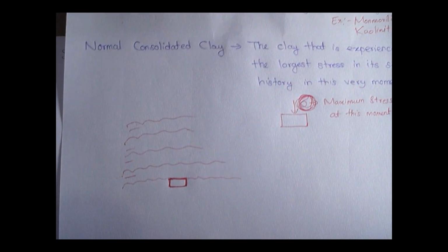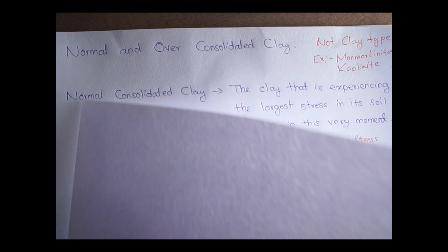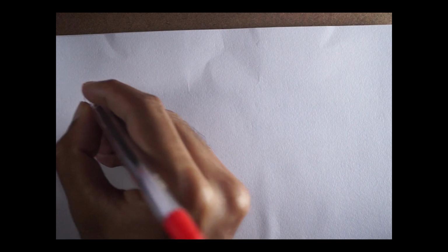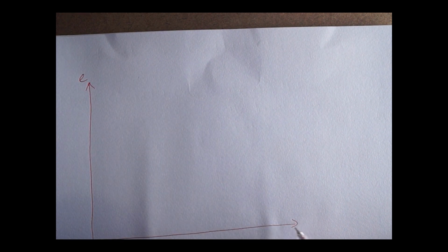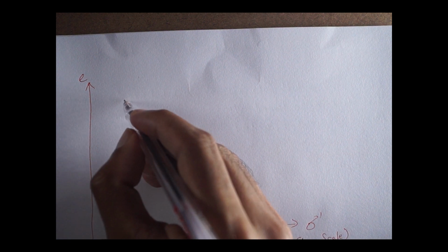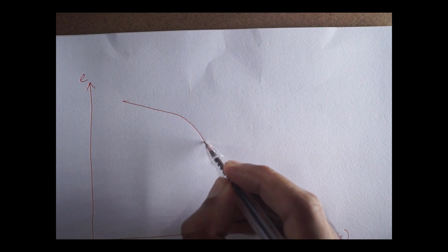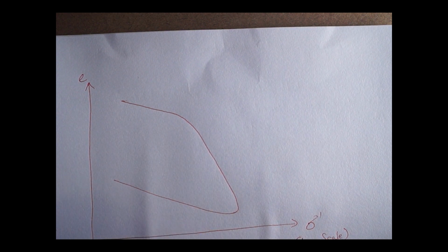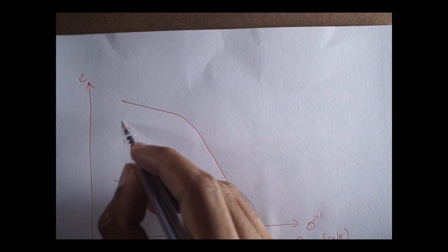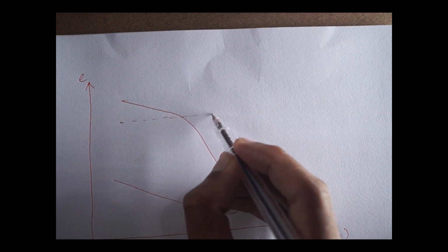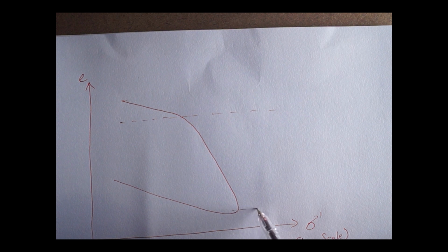So in our one-dimensional consolidation laboratory test, after performing the entire test, we would draw a graph for the void ratio e and the effective stress sigma in a semi-log plot. This would be in the log scale. So if we randomly draw a rough sketch of this output graph, this graph section can be divided into three portions. Three sections.